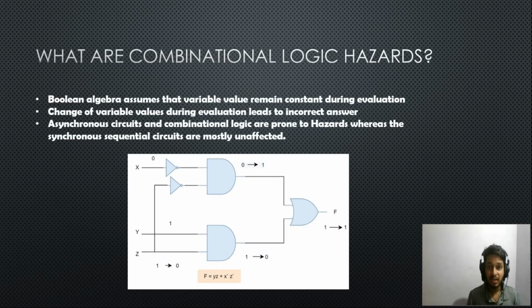What I'm trying to say is, let's say we are evaluating this combinational logic, which might be sent somewhere, or a sensor is reading the input from this OR gate, or some logic or flip-flop is reading the input from this OR gate. If the flip-flop takes the input from this OR gate after considering all the propagation delays, the worst case propagation delay, then it's fine, which means it is taking this propagation delay into consideration.